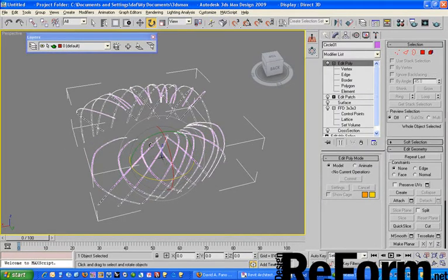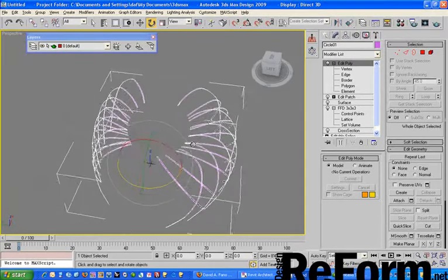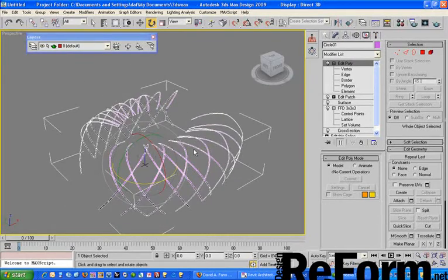Well, there's my kind of 2 cents at giving it a shot right now on how I'd go about doing it. You can get the curves out pretty easily, but then it's really by cutting up the surface this way, it's the easiest way to give it a thickness based on the normals of the surface, where if you do curves, it's going to be really hard to project it or get it to match. You could do a 2-rail sweep and put the profiles on each end, but that would require some sort of automation, which would be pretty tricky to do through the interface.